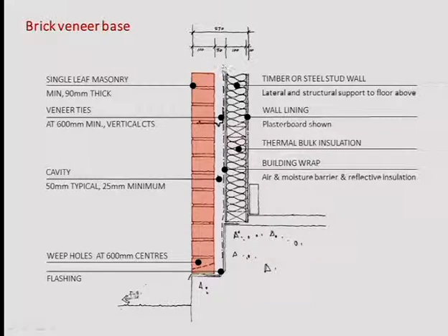So it's placed here. If this is a waterproof layer, it means that water can actually go there and then it's going to be collected down here. And then there is this flashing. This is just a dashed line here, but this is a metal element that is able to collect water and bring it out. Here there is a weep hole. So you see that there is a continuity in waterproofing so that water cannot access the house.